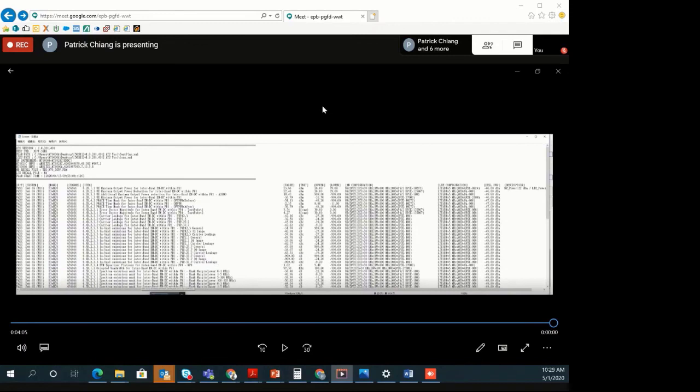So what's the longest test case time for an RF test case? I would say the receiver tests take longer than the transmitter. Transmitter tests are usually much faster than the receiver. So, for example, sensitivity, especially you need to do a search, right? That takes a long time. So what's the time frame that you can estimate?